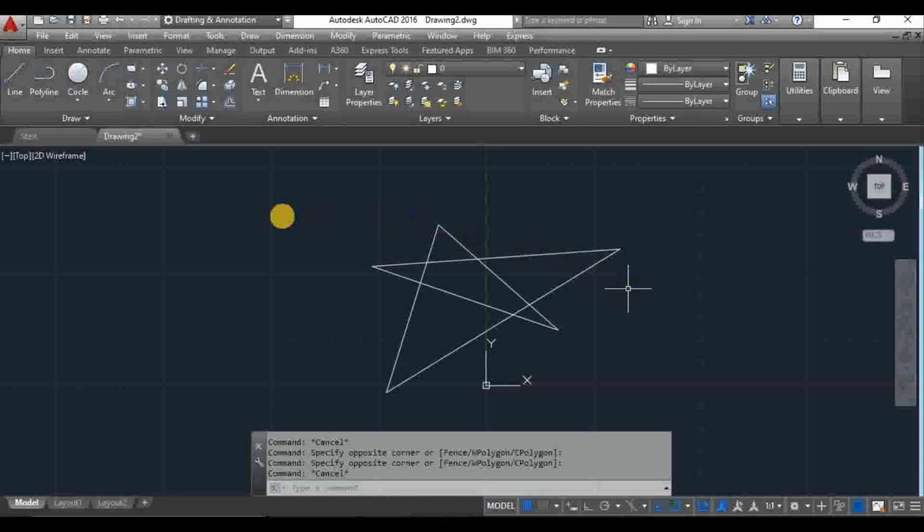When we use AutoCAD for various fields, we need to change units, as in case of mechanical, the units used are in mm, whereas in case of civil and architecture, we use feet, inches, or meters. So we will learn how to change or set these units.